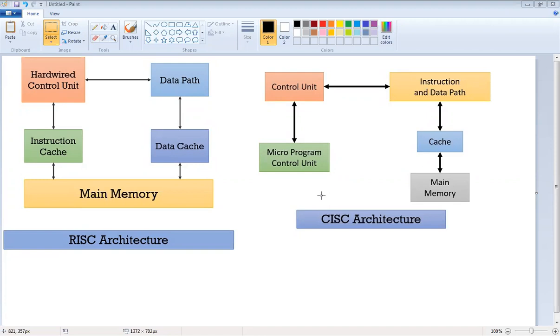So this multi-core processing is there in the ARM controller. It supports multiprocessing, mostly single cycle execution instructions are there, because it is a RISC processor. It has an enhanced power saving design. 64 and 32-bit execution states of scalability, high performance. Again, it supports a memory management unit and a memory protection unit. So MMU and MPUs are there in the ARM processor. Also, digital signal processing algorithms are supported by the ARM processor. So this is nothing but your ARM processor.